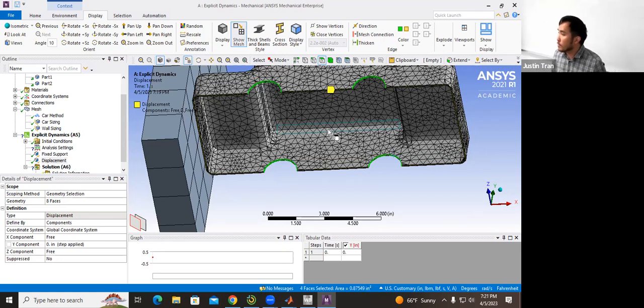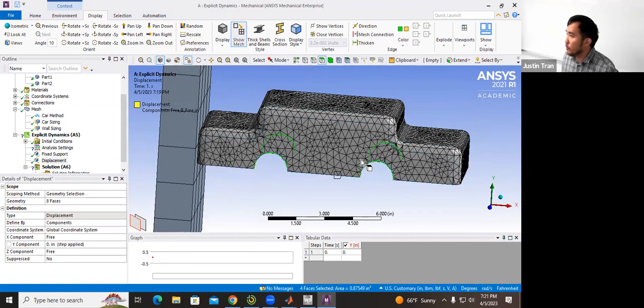Would that inhibit it from deforming in the Y direction? No, it will still deform in the Y direction. Or I should say, the top of the car could still flatten. It's just that these parts on the bottom are fixed onto a rail, but the rest of the car can squish and unsquish like that. It mostly prevents a rigid body motion. That's what it does. All right, any other questions on this here?